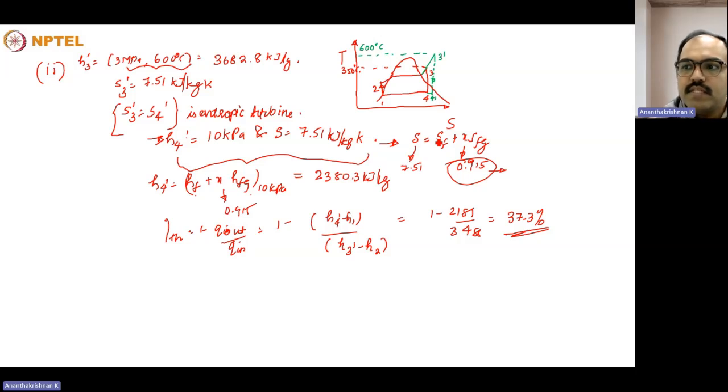This is because of the irreversibilities due to the temperature gradient. We assume that the temperature of the high temperature heat source is constant. And from there, when we try to add heat into the boiler to the steam side, the temperature gradient will be less when we are delivering it at a higher temperature. So what that means is that the irreversibilities associated with the temperature gradient will be less in the case of a high temperature one. So I know that it can be quite confusing.